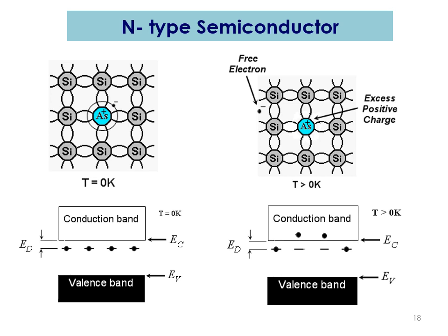This is another case of an N-type semiconductor. Here, the silicon was doped with arsenic, As+. Similar to phosphorus, arsenic also has an excess electron. The excess electron creates the donor level just below the conduction band.